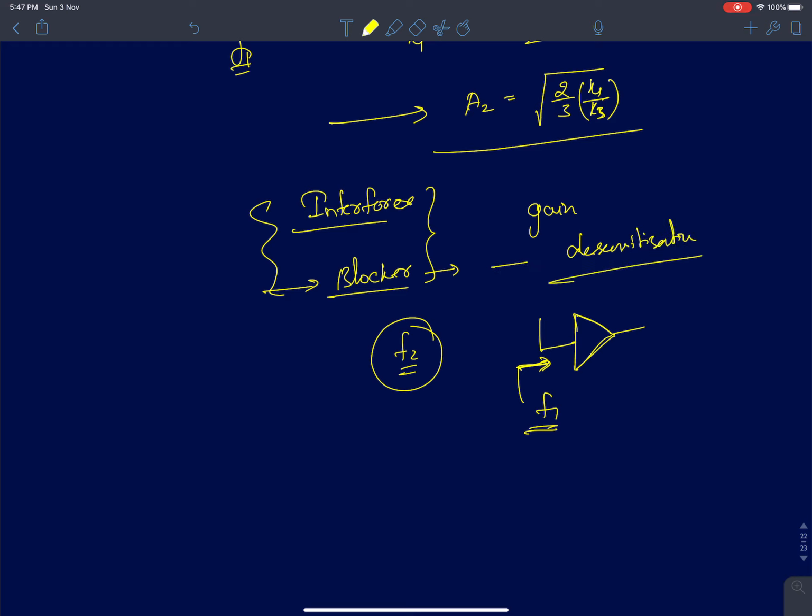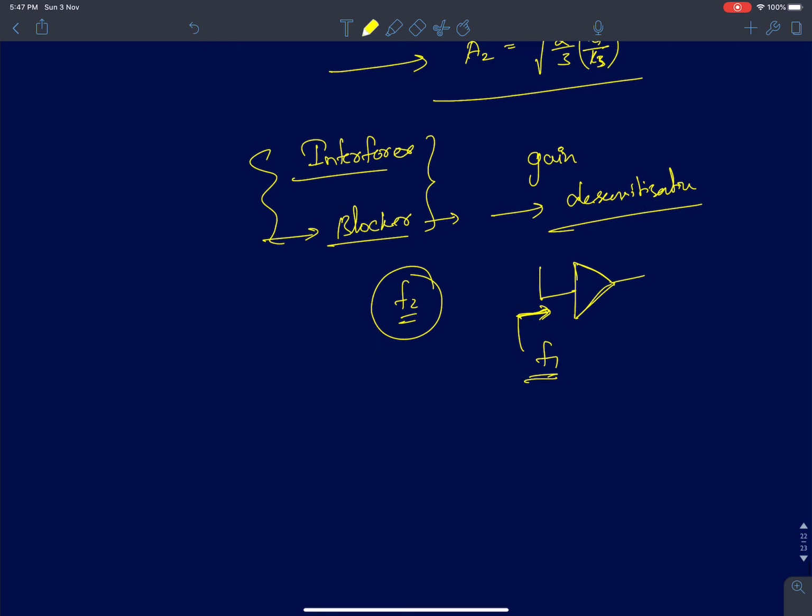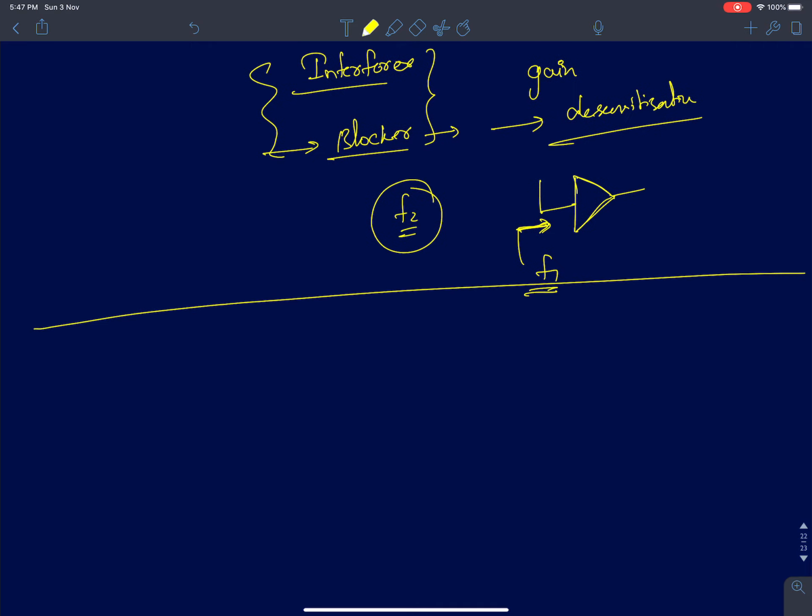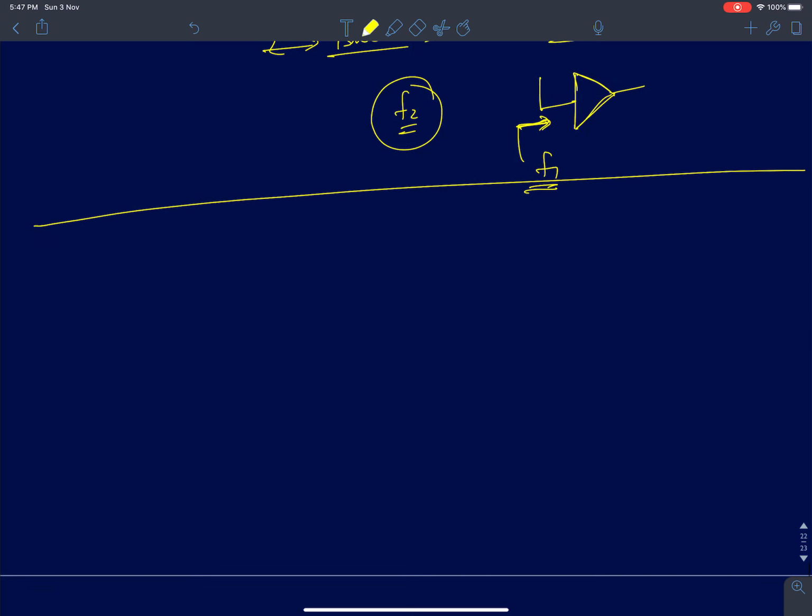Okay, so these are the problems because of nonlinearity, and as we said, this can be a very severe problem in RF circuits. See, this doesn't happen in low frequency circuits because we don't have the concept of interferers. But a strong interference can actually saturate your amplifiers. So far in our discussion, we did discuss interferers because interferers occur in wireless systems. I mean, you can't avoid them. One of the classic problems in RF circuits is the presence of interferers.